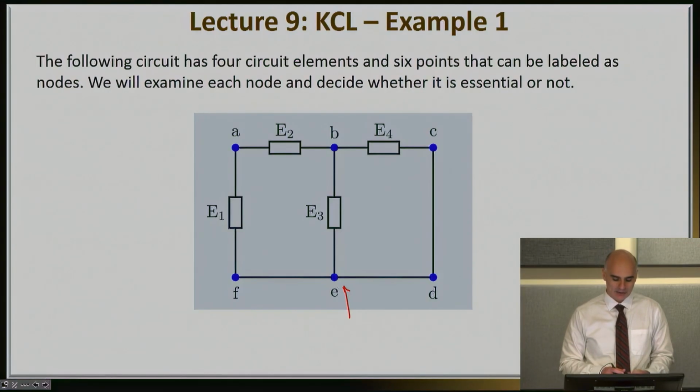I also want to remind you that really nodes E and F are exactly the same. Why? Because they're connected with a short circuit. I just highlighted this with red. So once again, it doesn't matter that they are not physically placed on a piece of paper or on the slide at exactly the same physical point. The very fact that there is a short circuit between them guarantees identical voltage between E and F, in other words, that the voltage in E will be the same as the voltage in F, and therefore, from an electrical perspective, those two physical points represent one electrical node.